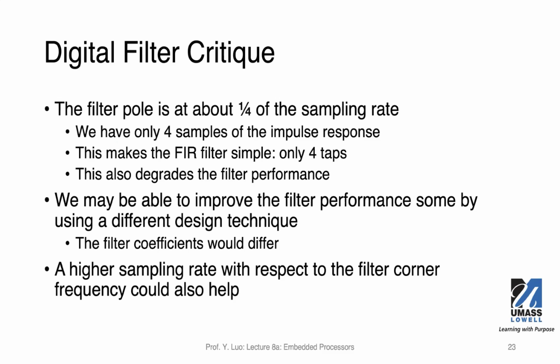But for our design, we use 4 samples, which makes the FIR filter very simple, with only 4 taps. And as a result, that degrades the filter performance.